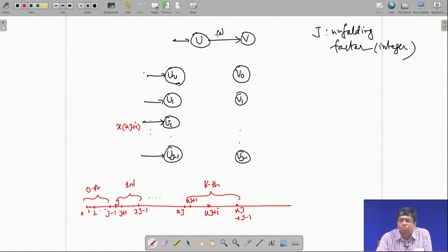by W number of input cycles. This cannot be violated, this is the original job. Whatever I do for digital implementation, in parallel or whatever, that is my business, but the original job cannot be violated. The original job was that every time you process the original input at the original rate, after that the output comes at the output of the processor, you have to delay it by W number of original input cycles, where the cycle period was T by J.